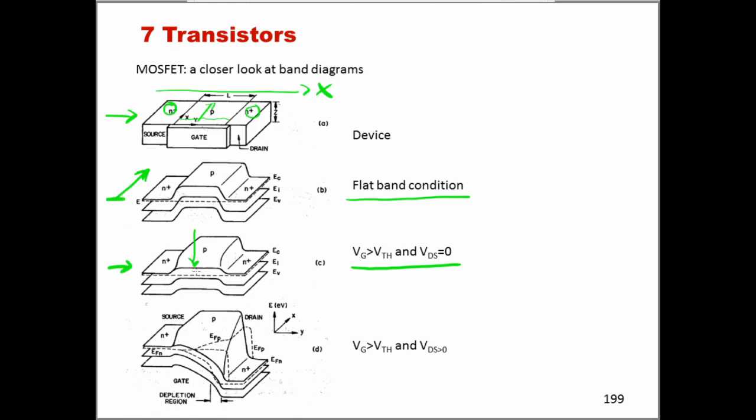We are making the Fermi energy that is here closer now to the conduction band. This means, as we said previously, we are inverting the semiconductor locally and turning it into n-type. And so now, electrons from the source or the drain using thermal energy could potentially overcome this barrier. Obviously now there is no VDS applied across the source and the drain, so there is no reason why electrons would prefer to move from one side to the other or the other way around. So the current in this case is 0.